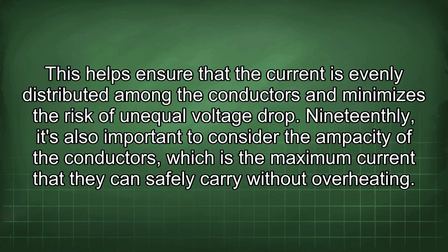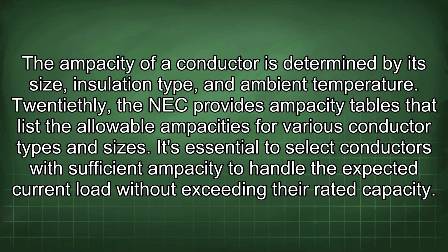drop. 19thly, it's also important to consider the ampacity of the conductors, which is the maximum current that they can safely carry without overheating. The ampacity of a conductor is determined by its size, insulation type, and ambient temperature. 20thly, the NEC provides ampacity tables that list the allowable ampacities for various conductor types and sizes. It's essential to select conductors with sufficient ampacity to handle the expected current load without exceeding their rated capacity.